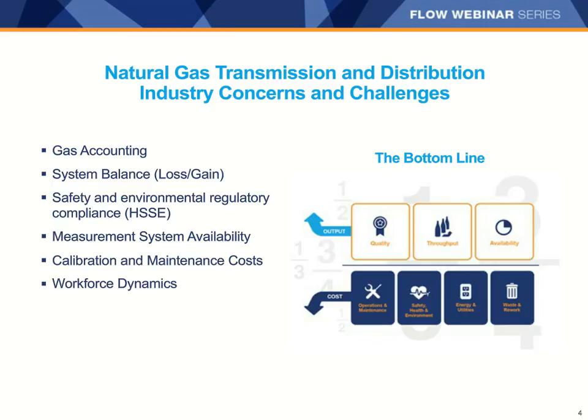As more and more sources of supply and uses for natural gas and its components emerge, the increasing variability of composition brings new challenges to accurate measurement for the technologies used previously. This includes the increasing probability that gas may dip below the dew point and liquids may condense, forming wet gas.